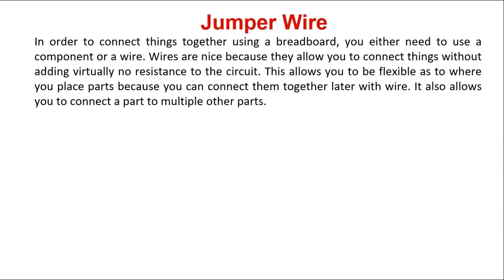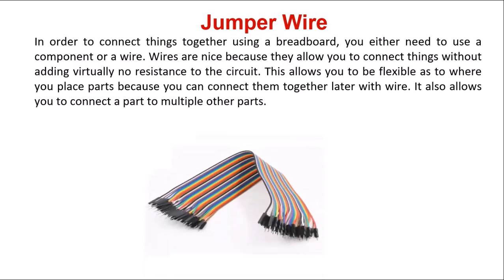Next, the breadboard has holes. We cannot use simple wires because they do not have enough strength to push and insert into the hole. That's why we need to use jumper wires. These types of jumper wires we normally use, and you can see here the end terminals have a steel body through which we can insert it.